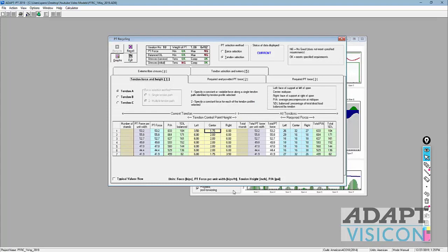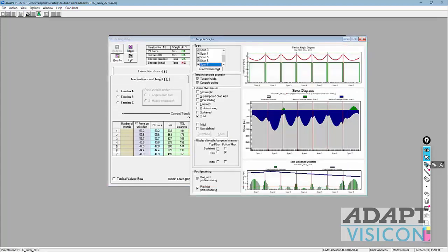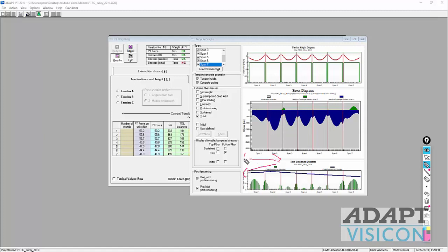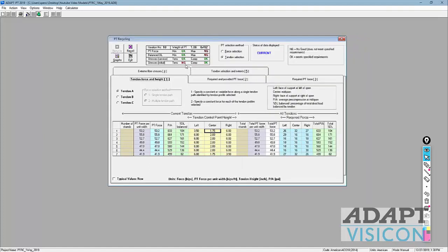Okay, and now what we see is this type of profile. So this is a varying profile. We're losing force as we move from live end over to dead end. This is live to dead, and this loses force. The average of this curve is roughly 27.2 kips. So it's actually more than the assumed effective force of 26.7. And that might be why this now fails.